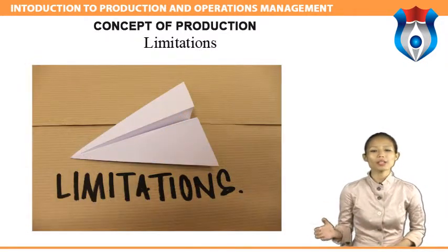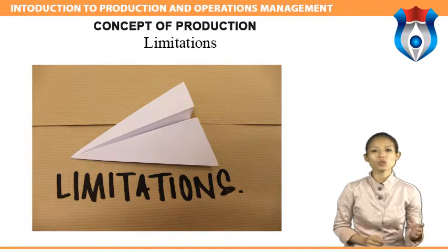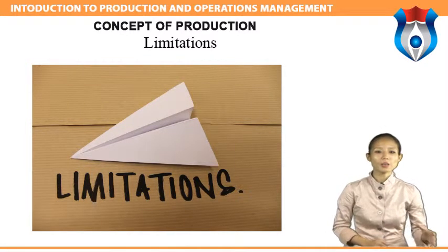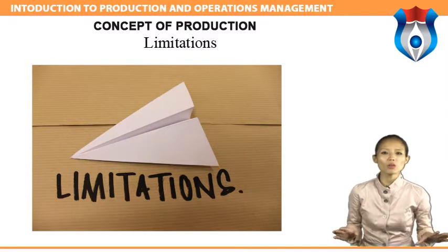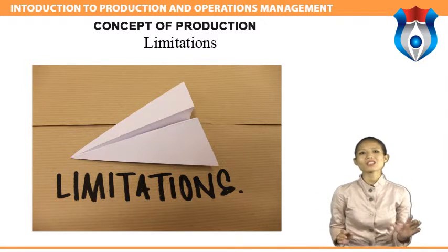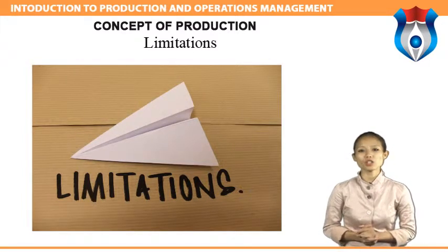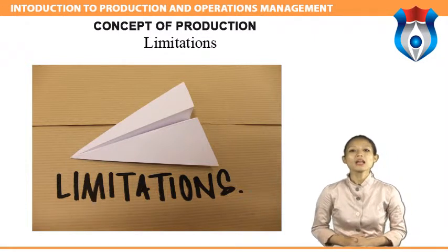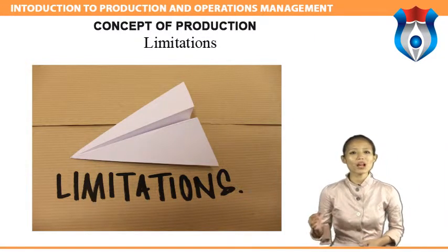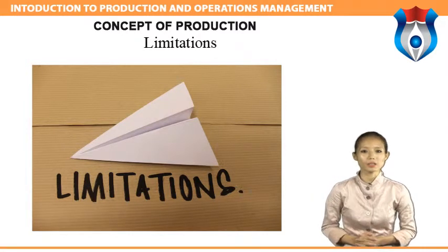Let's look at the advantages of continuous production. Standardization of product and process sequence, higher rate of production will reduce cycle time, higher capacity utilization due to line balancing, manpower is not required for material handling as it is completely automatic. The limitations of continuous production are: flexibility to accommodate and process a number of products does not exist, very high investment for setting up flow lines, product differentiation is limited.